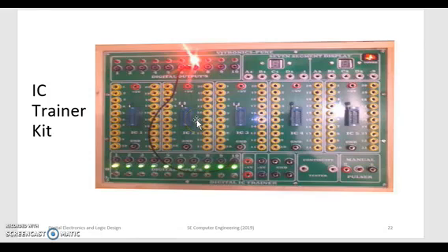Now for making connections, you always have to give ground and VCC for each IC. So this is for the ground. See, for each IC the ground is given, and for each IC the VCC is also given. Okay. In the next practical, where we have experiments to operate on pulse, we have to give the pulse manually. To give that pulse, see, this pulsar is also given here.